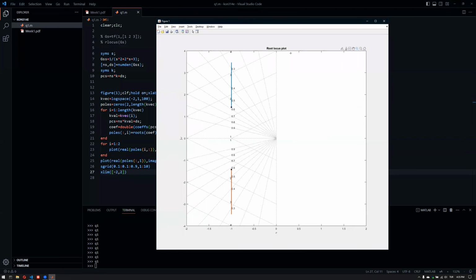Now, you see that the sgrid doesn't plot for the right half plane, for example. You can see that the zeta omega n pairs correspond to the left half plane. By definition, zeta should be something positive, omega n should be something positive. We call zeta the damping ratio, omega n the natural frequency, and the circles that you can see here, which don't really resemble circles for our case here, but I hope I'm going to improve on that, are the omega n values. And these slopes and lines are basically the zeta or damping ratio lines.